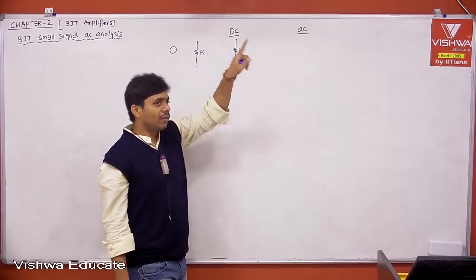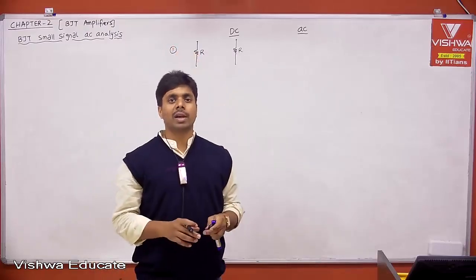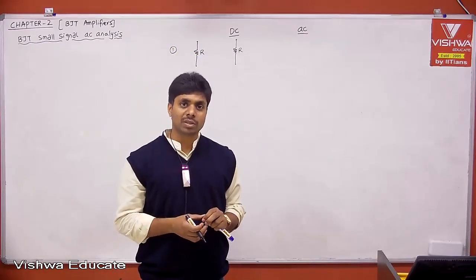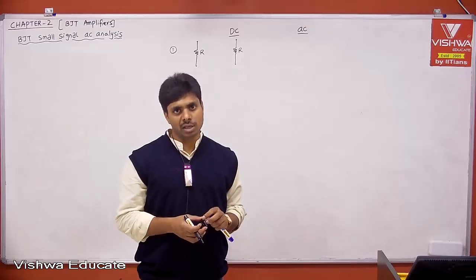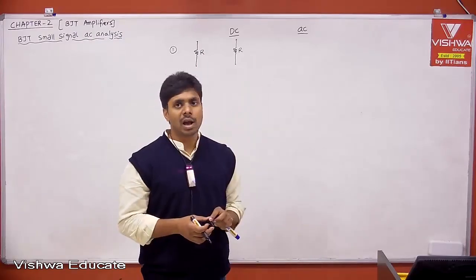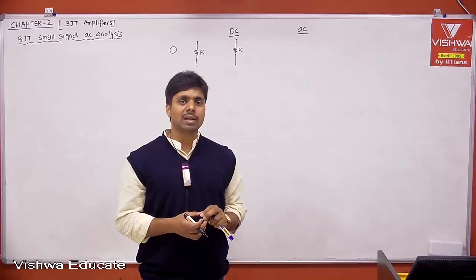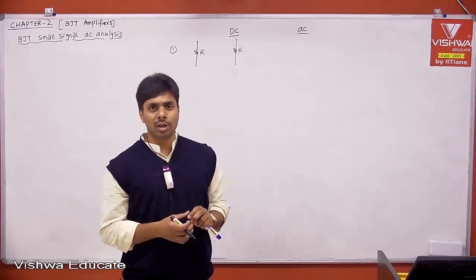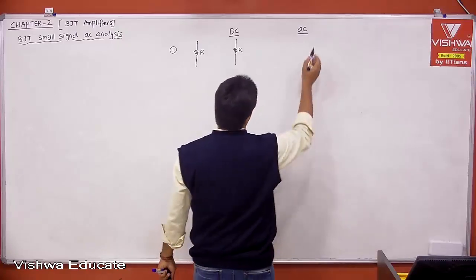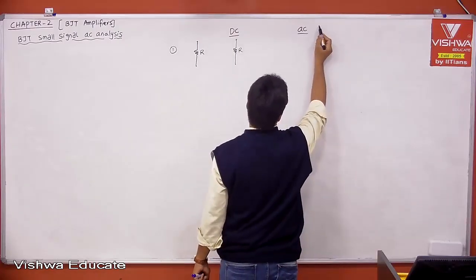But I told you at very high frequency, like hundreds of megahertz, like 800 to 900 megahertz or in the order of gigahertz, because of skin effect, the resistance changes, but I'm not going to that much frequency. When I say AC frequency or AC analysis, it is less than 100 kilohertz or less than 1 megahertz.